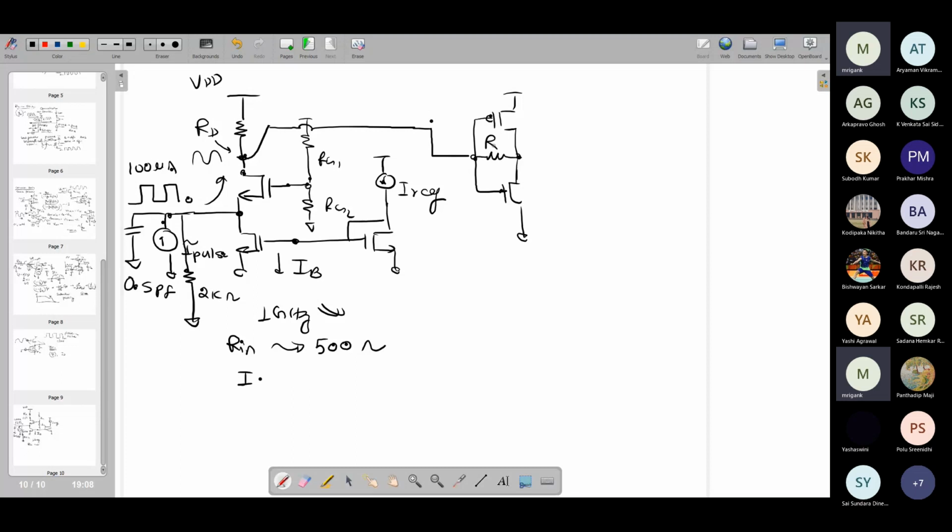So this particular thing, you will have to find out what is the R value. And if you do this, then the only problem is that the DC bias at this particular point will become coupled. So whatever DC bias you are having here and here, ultimately it will get coupled to the DC bias at this point. So then these values, whatever your R2 you are using over here and whatever RD you are using over here, R2 again, if you are at the moment shorting the input and output of this one, you will have a voltage division between this resistance and this resistance. So the DC biasing will be a little challenging.